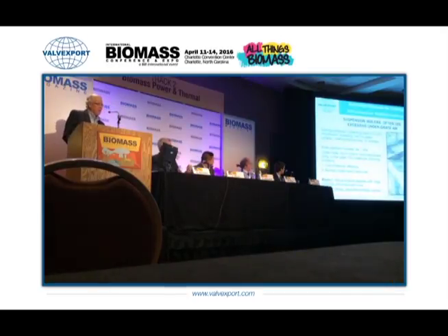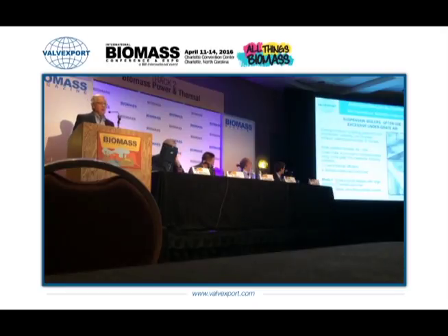We see in many suspension boilers that in order to minimize the amount of biomass accumulated on the grate, a lot of excess air is introduced into the combustion. That generates a lot of carryover, and we can see that at the end, when we clean the gases and collect the biomass that is carried over, lots of biomass is actually not burned at all.